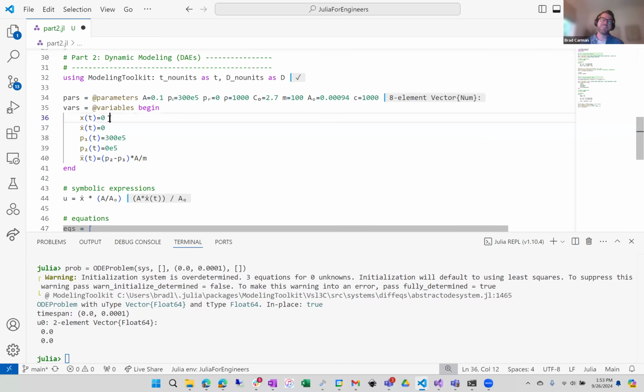Okay, sorry. So what we see here is that these expressions, when you list a variable and say equals, Modeling Toolkit now interprets that as an initial equation, okay? And so before, the definition of exactly how this expression was interpreted was more of a guess. It was called a default value, is actually the terminology that was used, but it was treated more as a guess value. And now this is treated more as an initial equation. So that's a very big change that occurred for Modeling Toolkit.